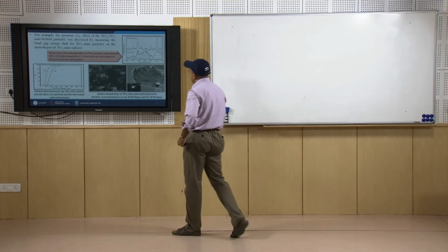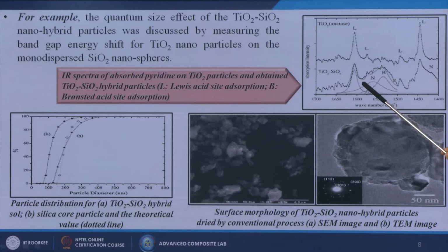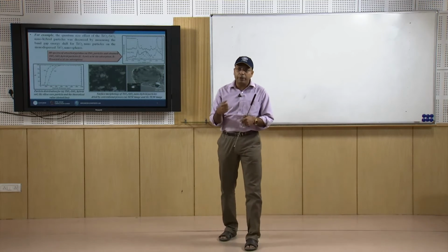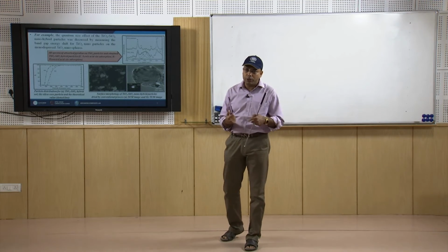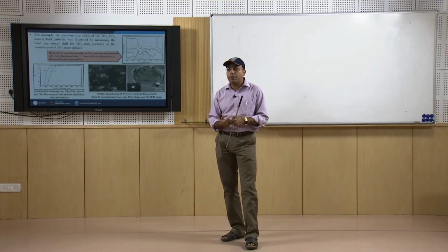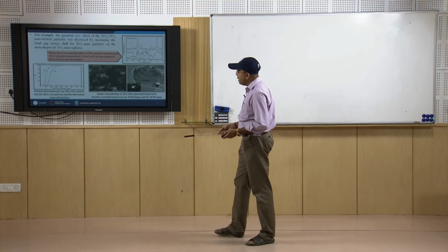When we are talking about TiO2, the next sample shows the TiO2 SiO2 hybrid composite, and from that FTIR graph you can see that some peaks have been shifted to the left-hand side, which shows better entanglement between the coating material and the substrate material, so that it shows better properties. How is it showing the better properties?